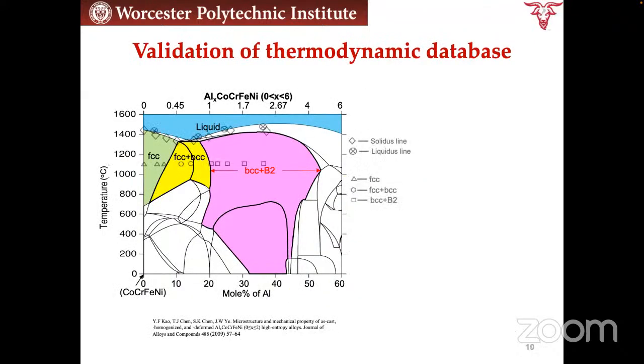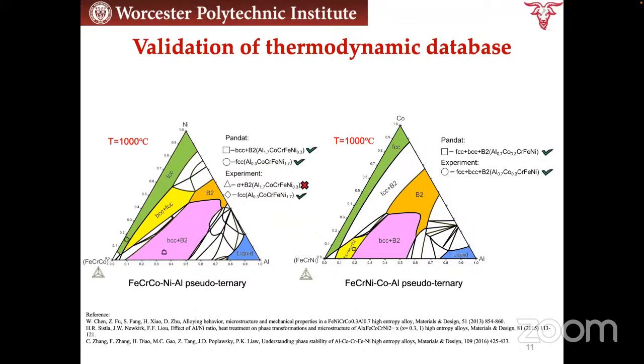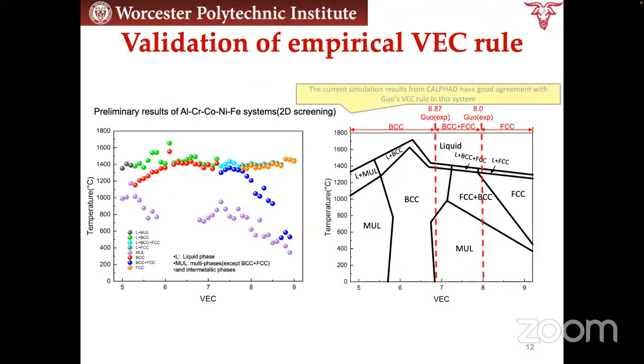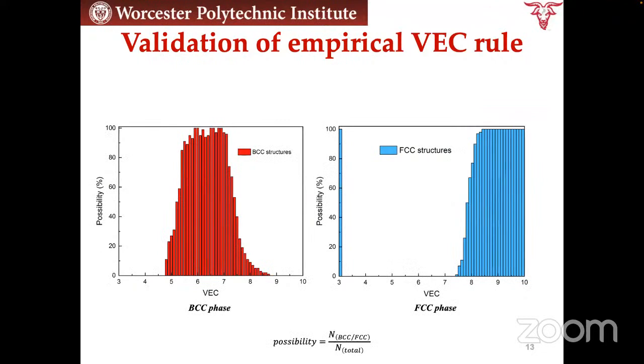So we borrow this concept, and we did a lot of simulations. We have figured out a way that we can do several thousand CALPHAD calculations. For the students taking my thermodynamics course, you will know, for the typical computational thermodynamics software, if we follow this traditional way, we do 1 or 2 calculations. But for these high throughput calculations, we can do thousands of calculations. And we are exploring a way that we can do 1,000,000 calculations now. So in this work, we did like 3,000 calculations.